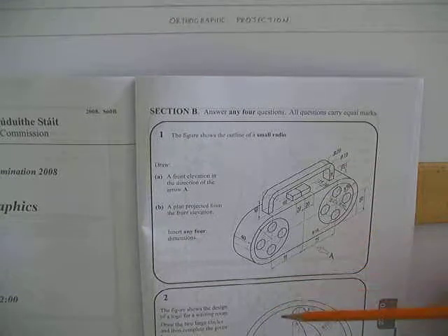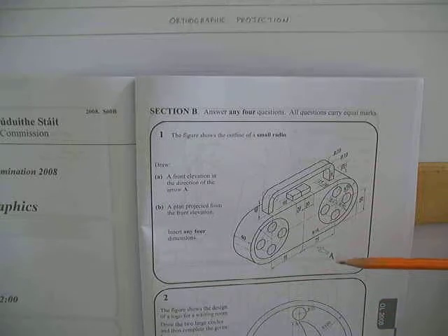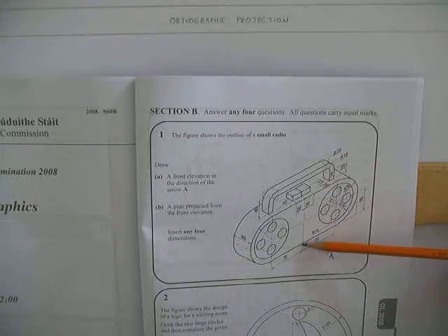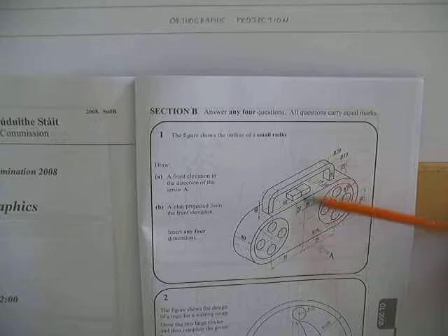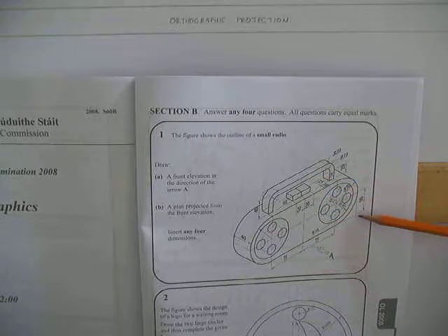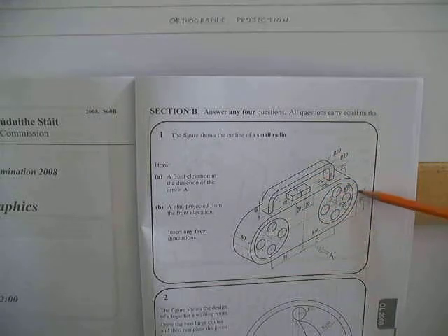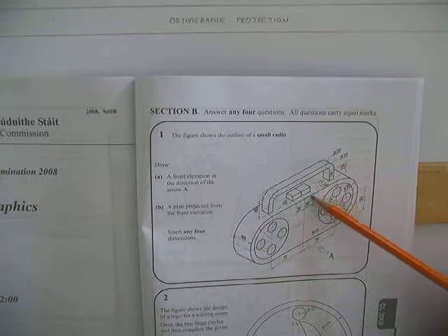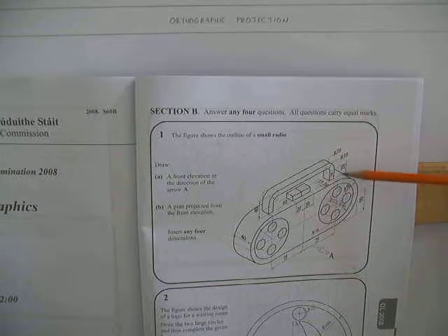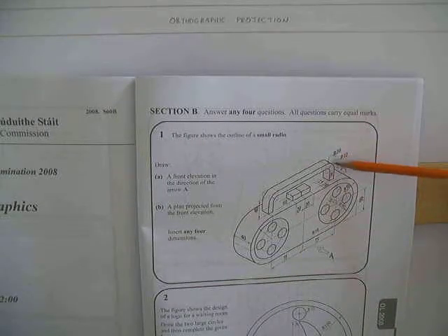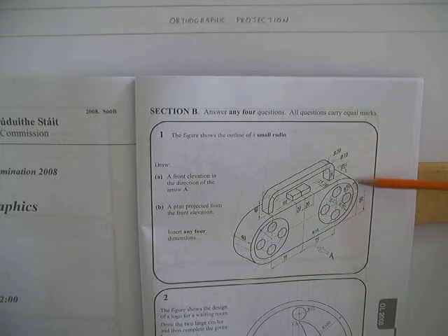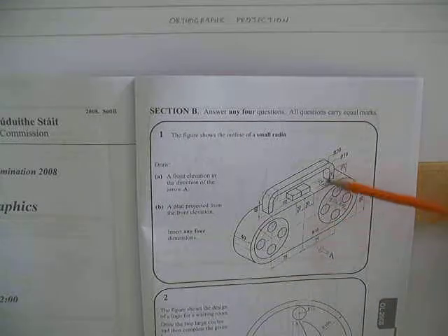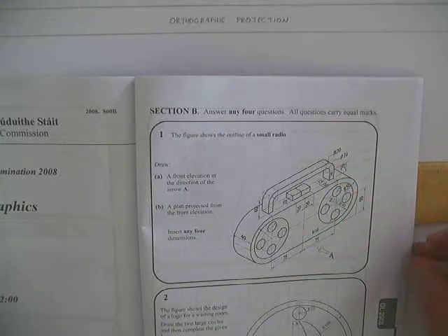So the first thing I need to figure out is the position of my XY line. So I must figure out, first of all, how far down the sheet I must come. So I need the overall height of the elevation. I can see here that the distance from the bottom of the elevation to halfway up is 50. That's a radius, so it must be 50 again, this line. That's 100 plus 20 plus radius 20, which is 40. So it's 50 plus 50, which is 100, plus 20 plus 20, which is 140, the total height of the elevation. So I'm going to come down 160 for my XY line.